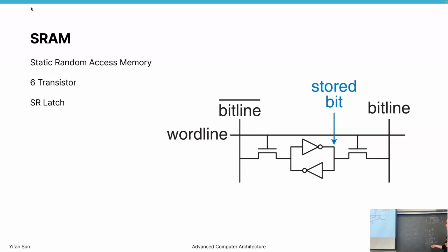So that's why we cannot really only rely on DRAM as the memory. We have to have SRAM, but SRAM is too small. We cannot have gigabytes of SRAM. So that's why we find a trade-off. We put more likely to access data in SRAM, and we put less likely to access data in DRAM. So it's a trade-off between latency and capacity. Okay, so that's why there's no single good technology to solve the memory problem. And still, the memory access latency is a big problem for today's computers.